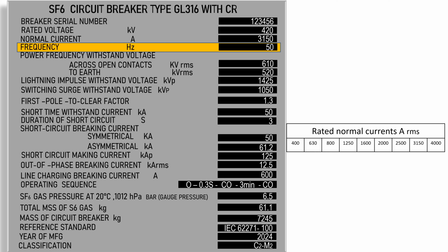The temperature rise of current carrying parts and neighboring metal parts is influenced by eddy current heating, which is further influenced by the frequency. Arc extinction during parting of contacts of the circuit breaker: frequency plays an important role, as the number of current zeros per second depends on system frequency.